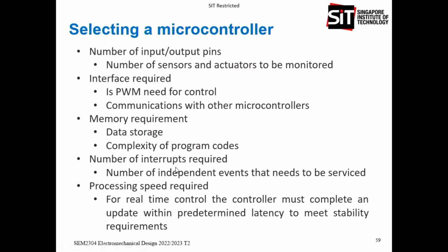Then for different applications, you may also require interrupts. What's the difference between polling and interrupts? Polling, basically, you need a microprocessor to go and check. So if I'm going to poll you guys, that means I'll check, are you okay, are you okay, are you okay? Then you reply to me. That's polling. But what's an interrupt? When you just talk. Some interrupts are good, you raise your hand, then you ask a question. But some interrupts are not so good, because you just talk.